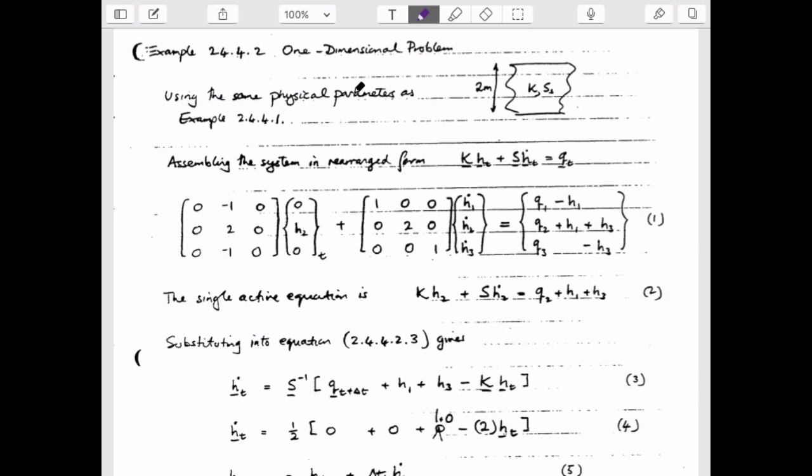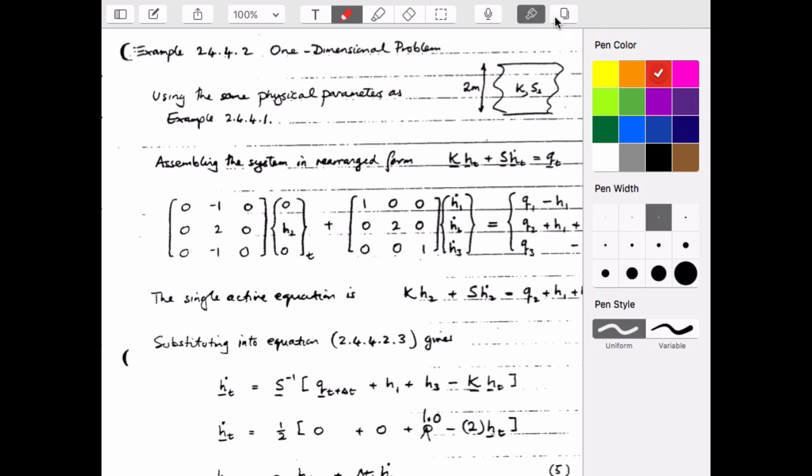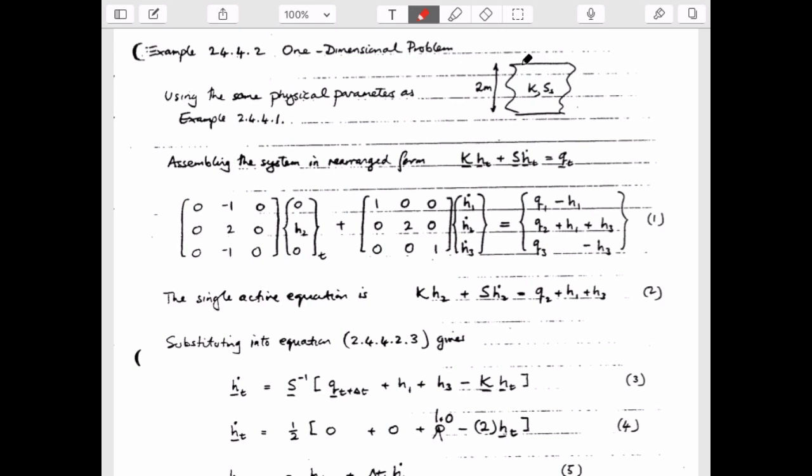So the obligatory 1D example is this. So go back to red. So the same geometry as before, something that's 2 meters tall. It starts off, I think, looking like with a head distributed that looks like this at a value of 1. At time t equals 0 plus, we put it to here, and ultimately over time it changes so that it goes from this to this to this. This is elevation, z, this is head, and the final value at the midpoint is a half.